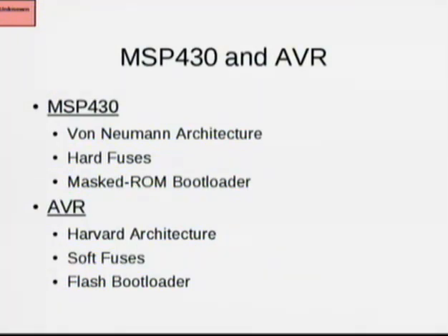This is in contrast to the AVR, which is a Harvard architecture chip. So you actually have 2 separate memories, one being flash ROM and the other being RAM. And a pointer might refer to one or the other. The only thing that specifies that is which instruction you use. And these are exploited differently. You can't write a simple Stack Overflow exploit for the AVR because you can't execute RAM.